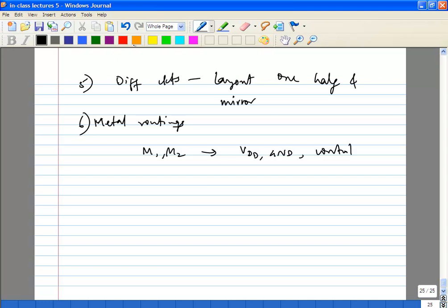You probably want to do, for example, substrate contacts, where you have to use M1. So at the lower level, as long as you don't have to route a long way, you can use them for VDD and ground. But if you have control lines, power on, power off, or gain control, those kinds of things, you can choose to do M1, M2.